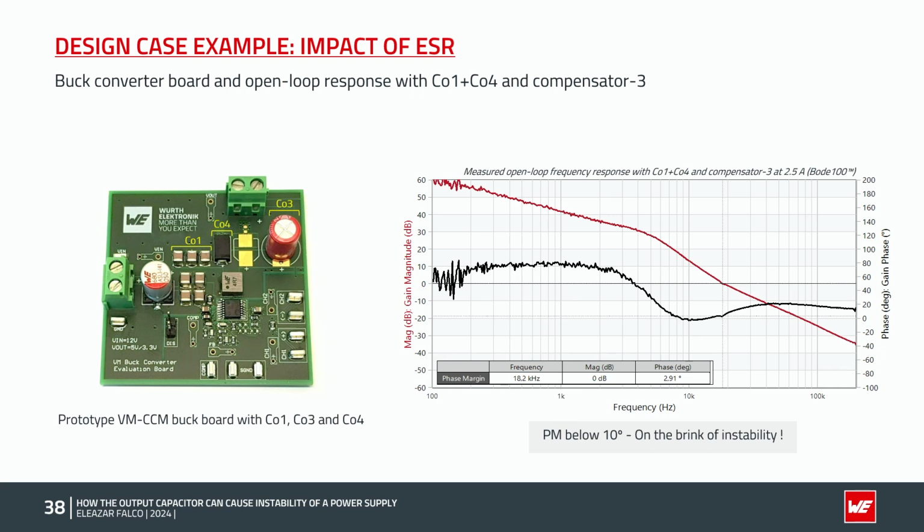We can see also that the curve here appears more noisy than before, and this is only due to the reduction of the injection signal to the minimum possible so that we can actually measure the frequency response in these conditions. Otherwise, we get problems with overload. So now the system is on the brink of theoretical instability, but we might wonder if the converter can still operate properly in these conditions. Now let us see.